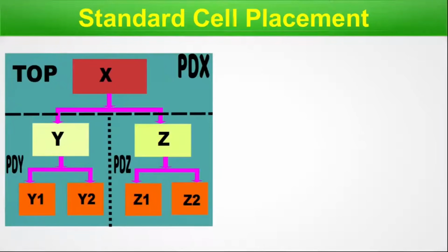StdCell placement. Let me bring my mouse pointer. Here you can see this picture I have shown you in the last episode. Power domain X, power domain Y, power domain Z, and inside, if we go down, we have Y1 and Y2. Here we have Z1 and Z2. So this is PDX, this is PDY and PDZ, and here is our boundary.